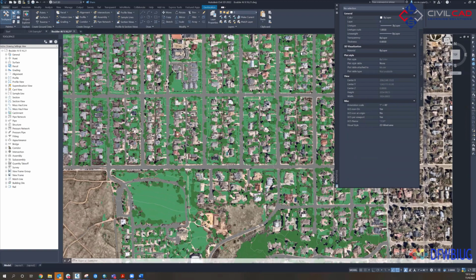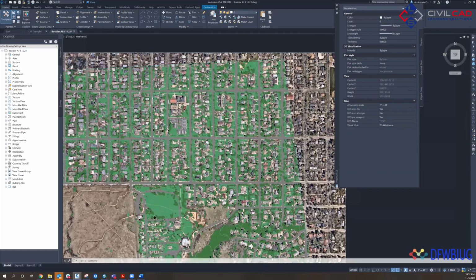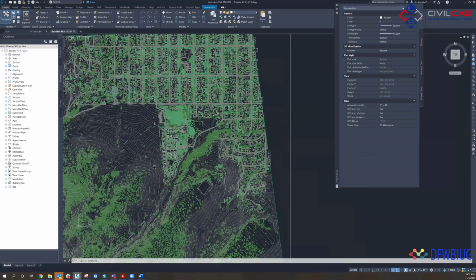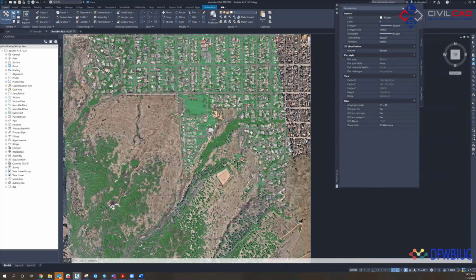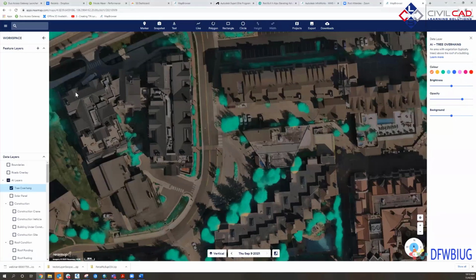So, yeah. Something else I've loaded in here too that I wanted to show is some contours. We don't offer them out of the box, but I was able to generate these off of some of our new 3D. We're doing a digital elevation model and a digital surface model. These were created using the Create Surface tool within Civil 3D off of the Nearmap DEM. Oh, wow. And is that something available now or later? It's available now. Oh yeah, that's always beneficial, especially when you're doing site planning and we need some crane contours and stuff like that.